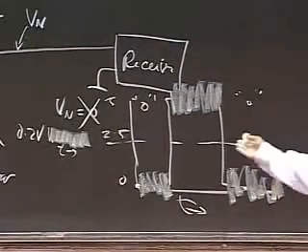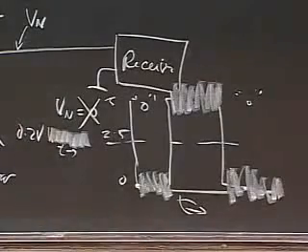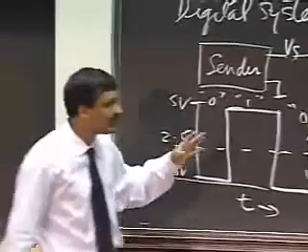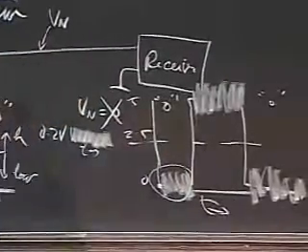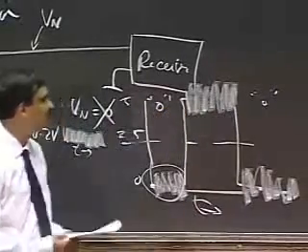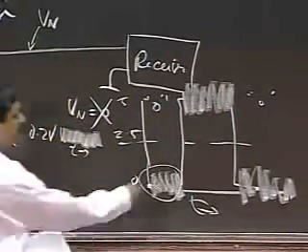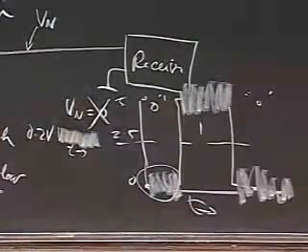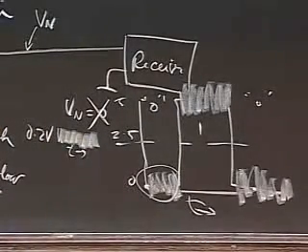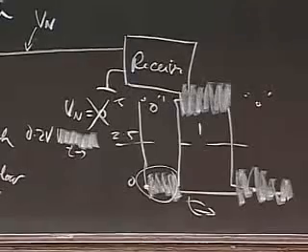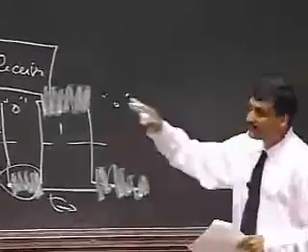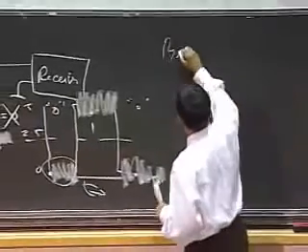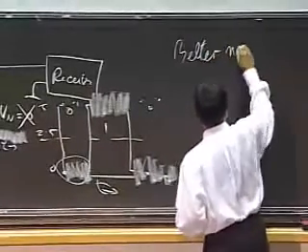So the receiver gets that signal, because the noise is added into my signal. But guess what? No problem. The receiver says, oh yeah, this is a 0 because the values are less than 2.5. This is a 1 and this is a 0. 0, 1, 0. So here my receiver was able to receive the signal and correctly interpret it without any problems. Because I used this value discretization and because I had this agreement with the receiver, I had better noise immunity.